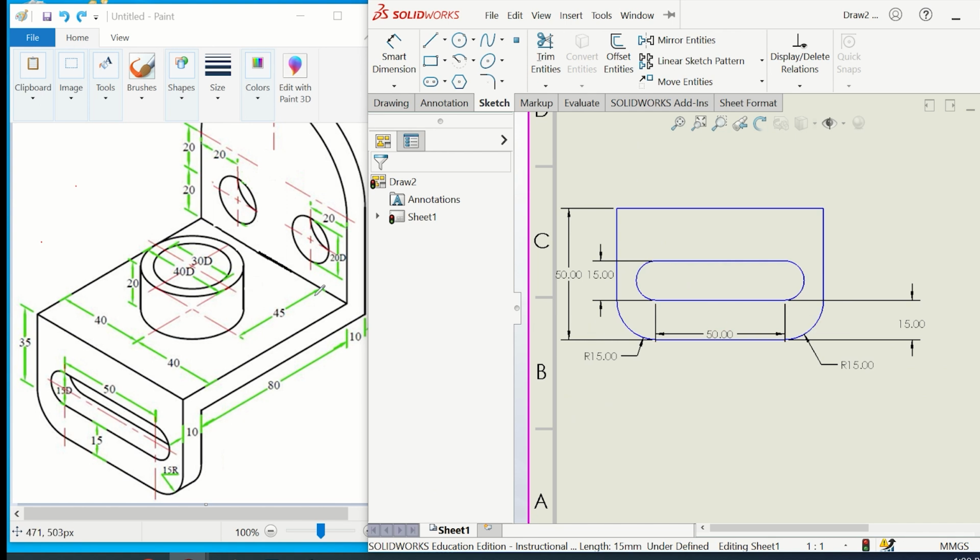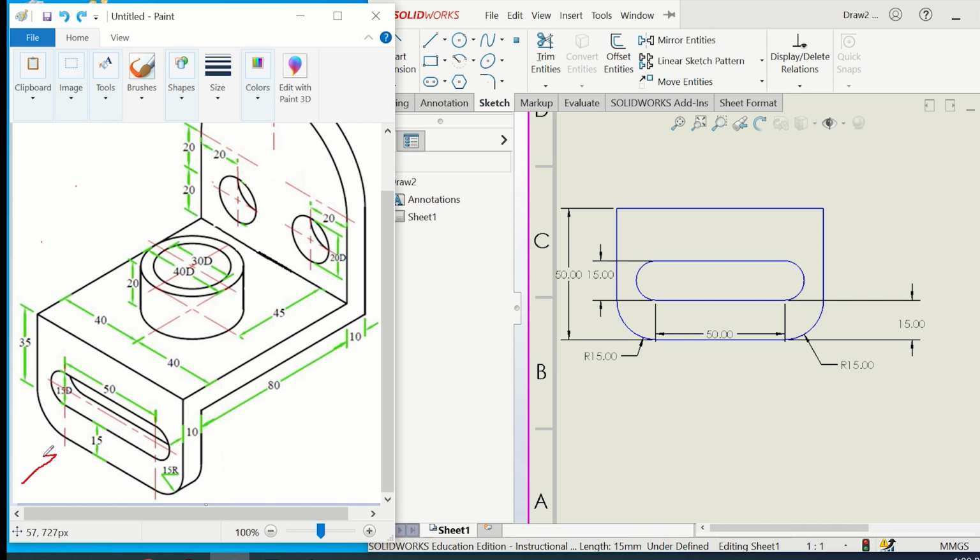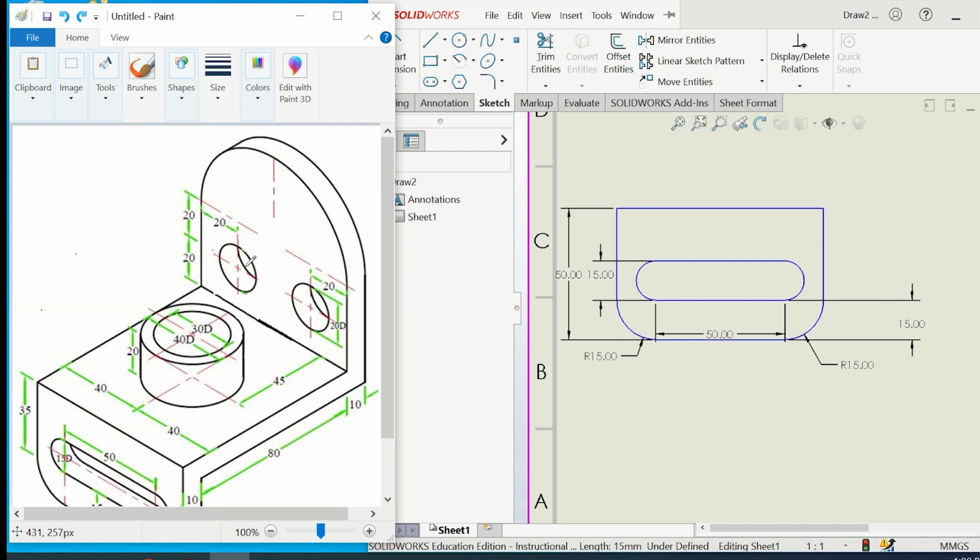Now, here, what else do I see looking from the front? Of course, I wouldn't be able to see this surface here from the front. However, I will be able to see this cylindrical face here, and I would be able to see all of this section here. So I'm going to draw the biggest one of these two, which is this thing here.